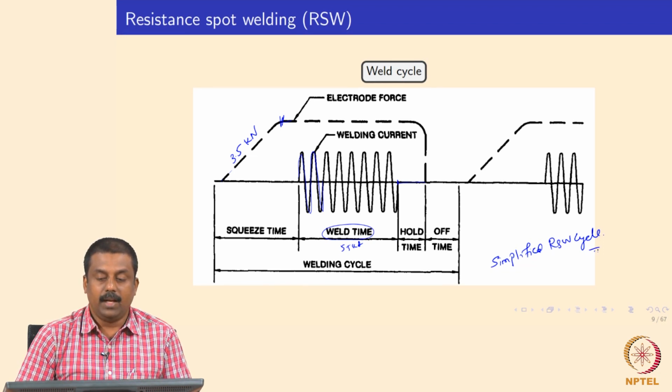So far, to summarize, we looked at the important welding processes that are used in the automotive industry. There are three processes commonly used nowadays: resistance spot welding, laser beam welding, and advanced gas metal arc welding, mainly to weld dissimilar weld discs.